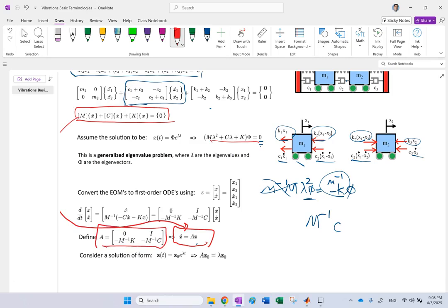Well, now if I go back and assume an exponential solution again, except for phi, I just call the mode shape for z, I call it z0, or you can call it capital Z or whatever, and e to the lambda t. If I plug it in, z dot is going to be what? Is going to be lambda z naught e to the lambda t.